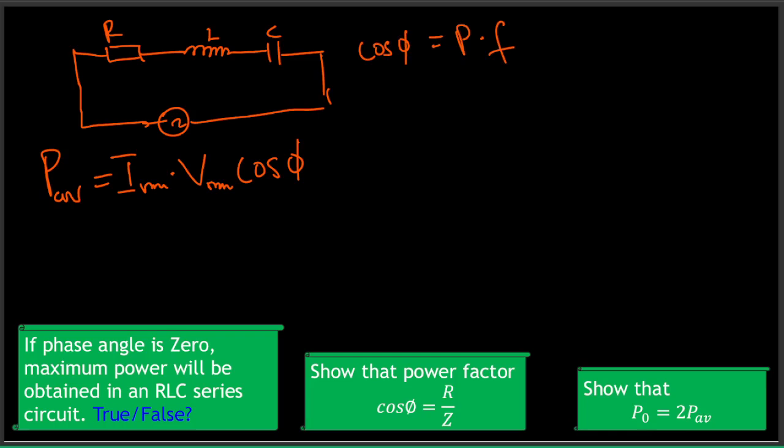All right. Now you can as well write this in terms of the peak, but let me give you the second formula. So average power is also, if you want to write it in terms of current and resistance, of course, I squared, but it's the RMS value times R. So these two formulas, I need you to take note of them. That doesn't mean that we cannot rewrite this. We can as well have, remember what this is.